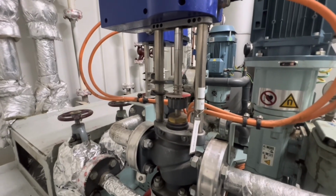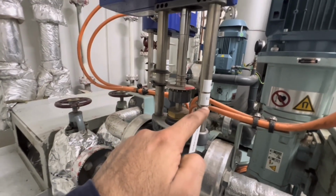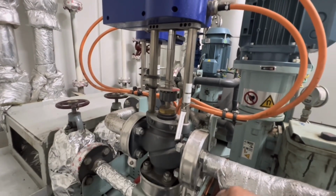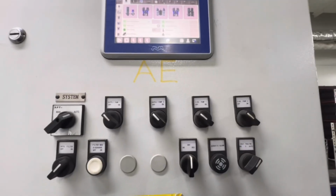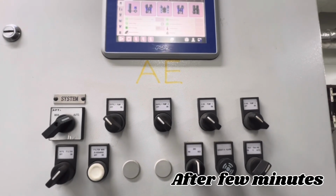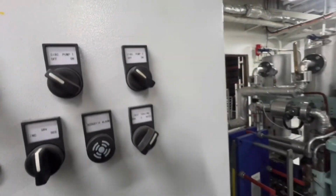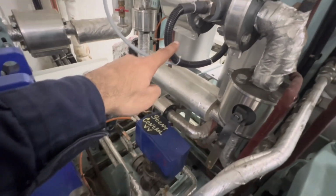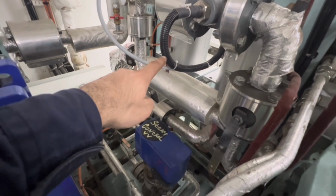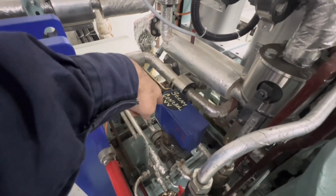So guys, now you can see that the valve has completely changed from heavy fuel oil to the low sulfur. So now the low sulfur fuel oil will be passing through the supply pump, circulating pump and to the system. See that the temperature has started falling from 132 degrees to 125 degrees. And how this is possible is with the help of viscosity sensor and with the help of steam controller. So this viscosity sensor detects the viscosity and gives a signal to the steam controller to reduce the quantity of steam passing through the fuel oil system.